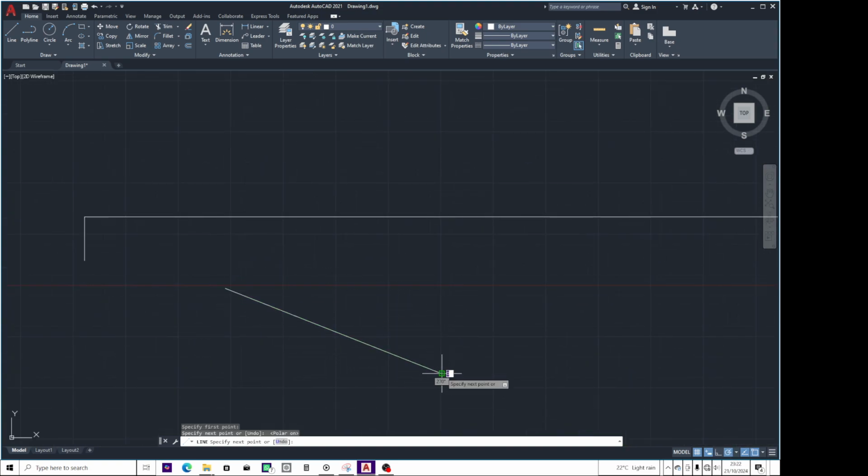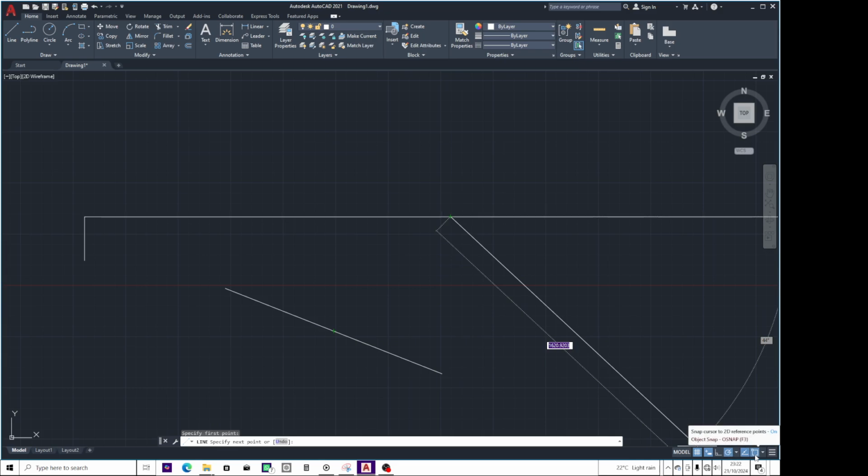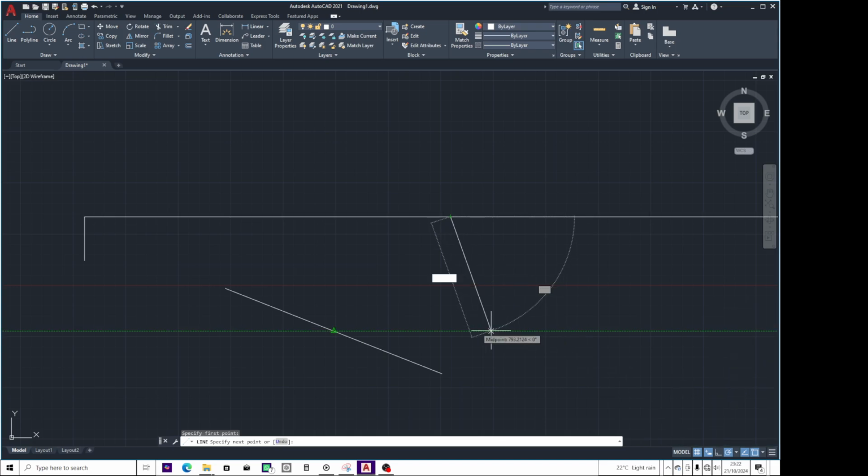This is some inclined line, and I need to draw a line perpendicular to this one from our center here. Once I come, I can't find the angle properly, so you go there, here, and right click, then activate your perpendicular there. Then once you mouse over,